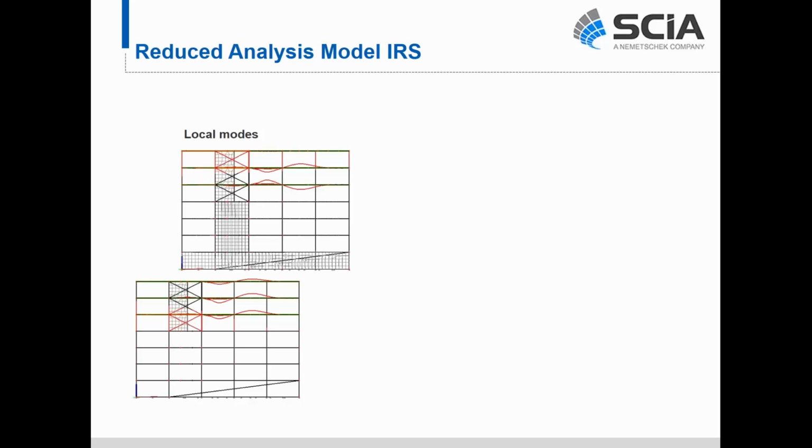And so what this aims to solve is that typically we have local modes in a structure. This is that same structure that we were looking at. We have these local modes that are just a vibrating or sinusoidal curve on a set of beams or a couple different beams. And this creates additional eigenmodes, which don't have an impact on the larger structure. And so we really want to filter these out.